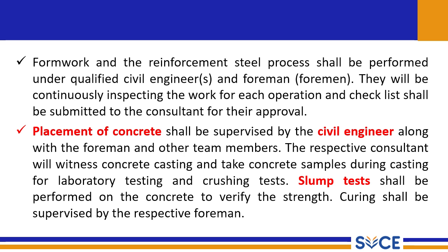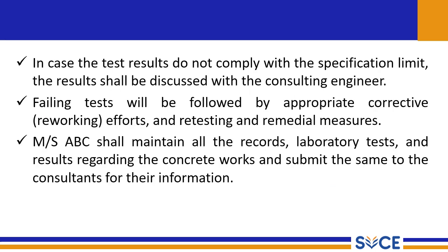It should be supervised by a civil engineer, under supervision of the engineer. And a slump test can also be performed on site to verify the strength or workability. Curing shall be supervised by the respective foreman. In case the test results do not comply with the specification limit, the results shall be discussed with the consulting engineer. The failing test will be followed by appropriate corrective efforts, retesting and remedial measures.